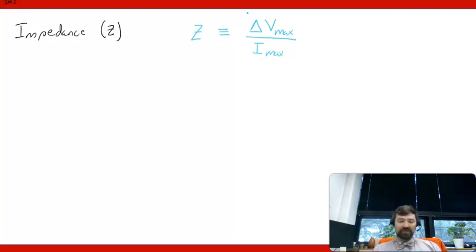And then having determined what that maximum current is, I can apply it to each of the elements in turn, using their individual reactances, to figure out what the maximum voltage drop across each of those elements will be. And I also know when it will occur for each element because I know what the phase relations are with the current.